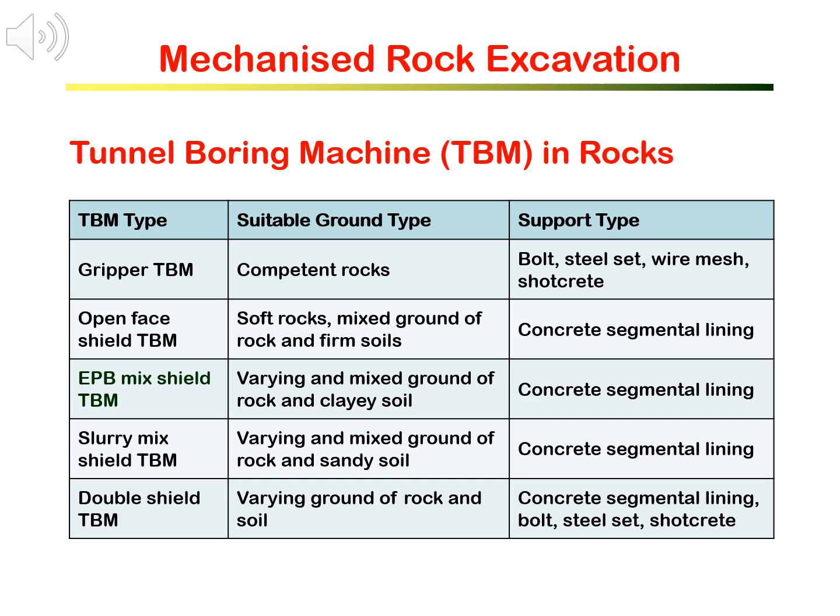Tunnel boring machine, or TBM, for excavating the ground with rock can be divided into two major groups: grip TBM and shield TBM. Grip TBM is really for excavating the rocks only, generally for competent rocks. Common shield TBM can be open face, EPB, slurry, or double shield.